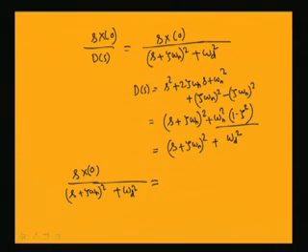To find the inverse Laplace, I can add and subtract the zeta omega n term. In the denominator you have s plus zeta omega n, so in the numerator also you should have s plus zeta omega n. So, you can add s plus zeta omega n in the numerator and denominator.